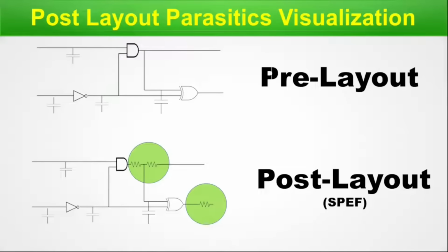Here I have only shown the resistors. However, there will be capacitors. All these things will be there. Now, once we do this post layout static timing analysis with all the resistors and capacitances from SPICE annotated into the simulation, we get a much more realistic delay, and that helps us to fine tune our design. That is the realistic part of the design. So I think I discussed here in a short and sweet manner what the post layout parasitics are there for. So with that note, let's move on to the next slide.